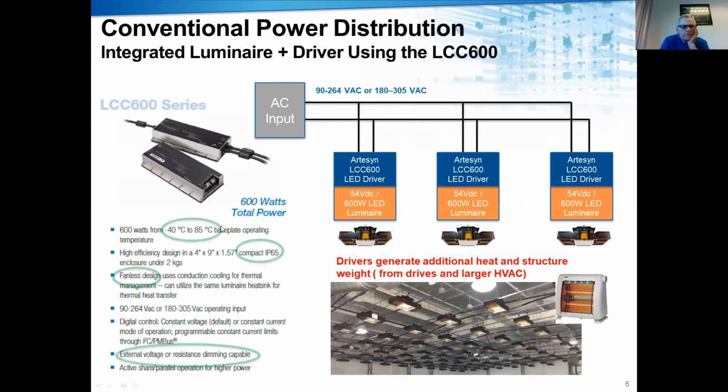As was discussed, if you do use drivers, they should be IP65 so they can get wet, and the temperature range has to be pretty high. Ideally you shouldn't be using any fans, but basically we were using drivers. The drivers produce a lot of heat within this area, and that's how we talked to Spectrum King. We were saying, how do we reduce the heat?